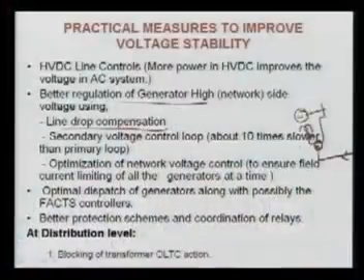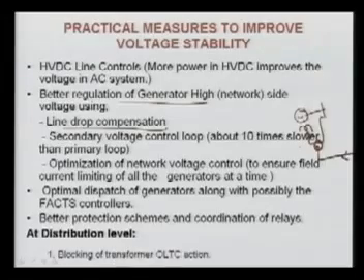If your current is hitting that maximum value, we cannot operate at more field current, because it may damage the field winding, as heat will not be dissipated. So it is called the field current limit. What we can do is have a complete coordination of all the generators. It is not that we keep on increasing the excitation of one generator while the other generators are not changing.